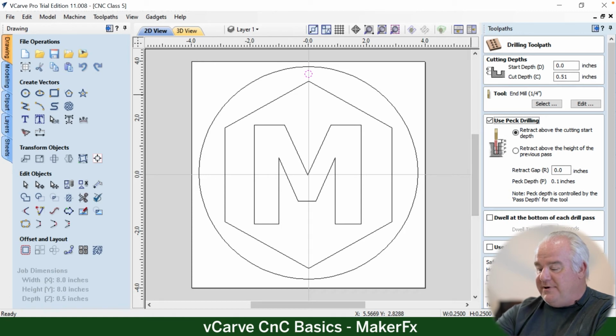So I want to show you pecking so that you can see it. Again, we won't see it on the 3D rendering in the software. When we operate the machine, we're going to keep the dust shoes off. There are 4 different dust shoes, and we're going to keep them off so you can actually get an idea of what it's doing. But just visually, you'll be able to see the machine peck.